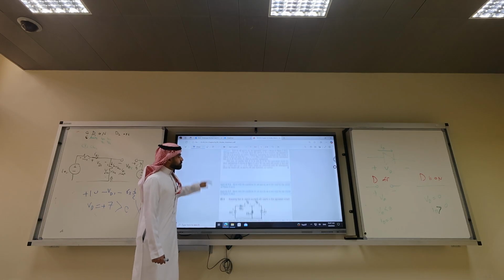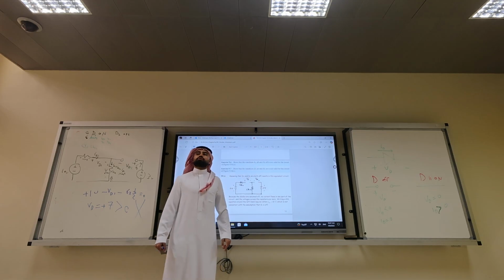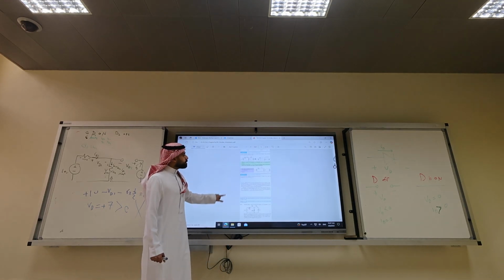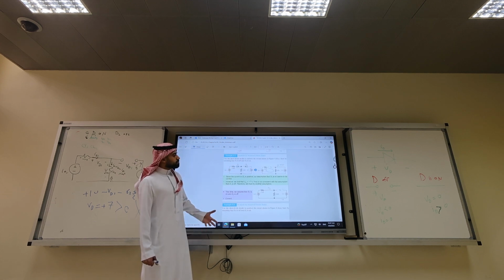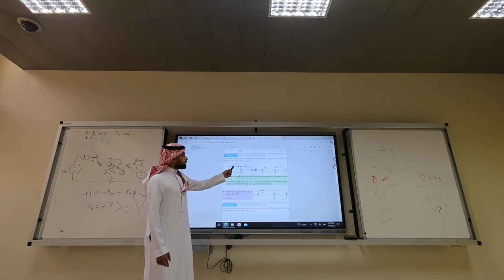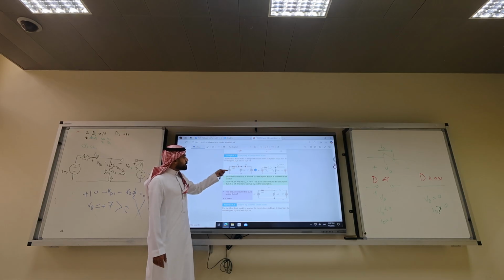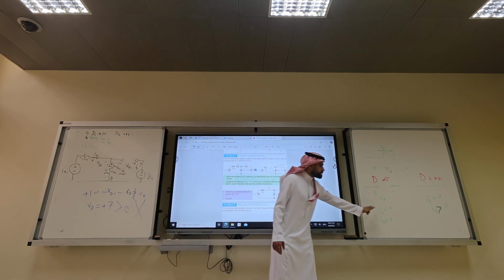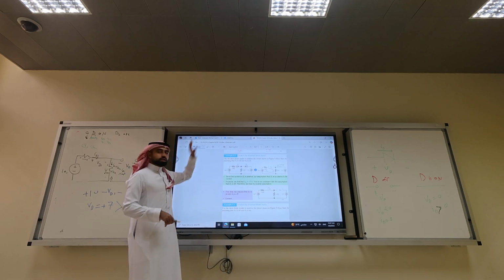In the slides, it asks you to show what if both on or both off. If both off, what will happen? Open circuit, open circuit. So ID is 0, satisfied. But I guarantee you, if this is on, the voltage here is 10 volt applied on D1. If this is on, no current. 10 will be applied to D1, and this is larger than 0. So VD1 will be larger than 0. So one violation, this assumption is wrong.